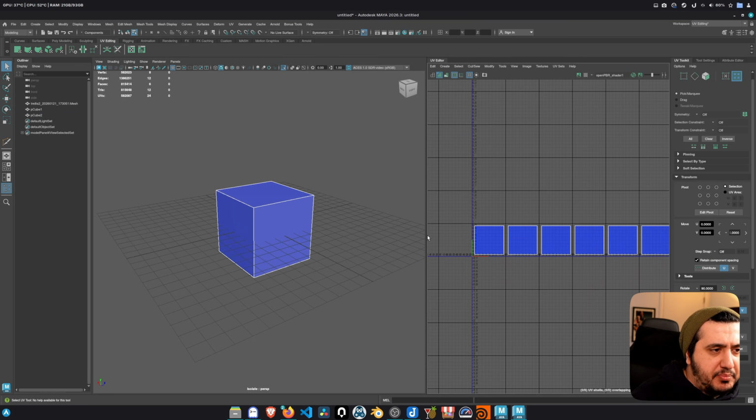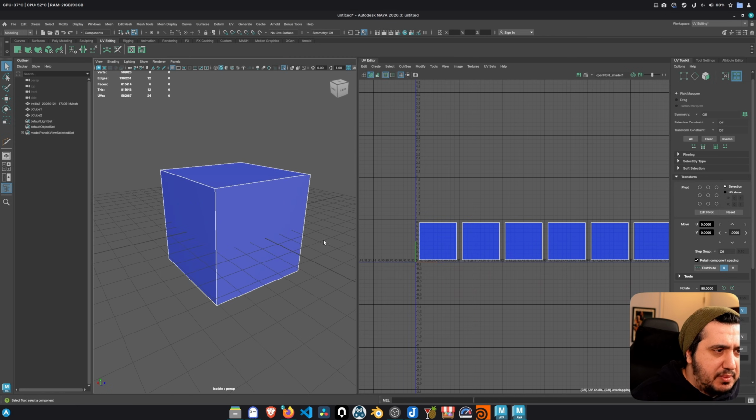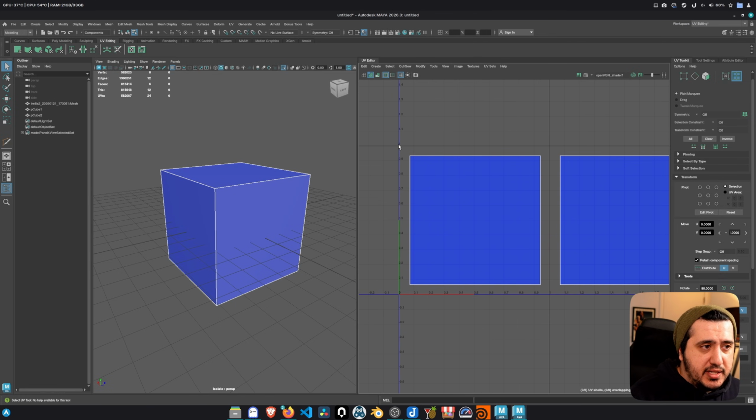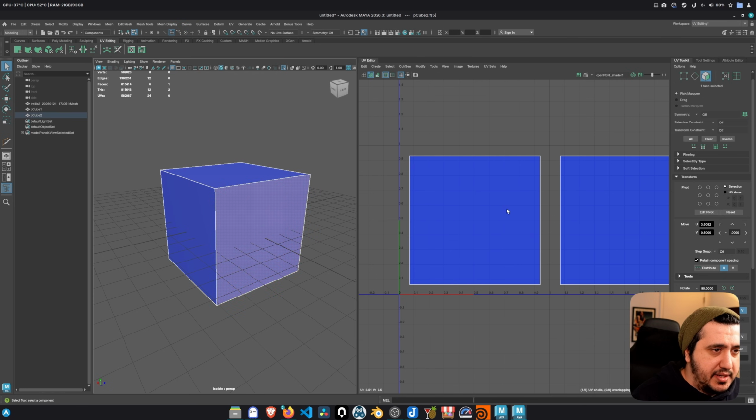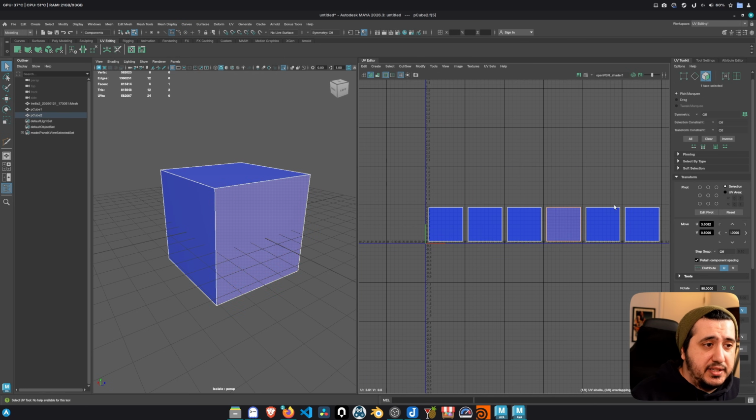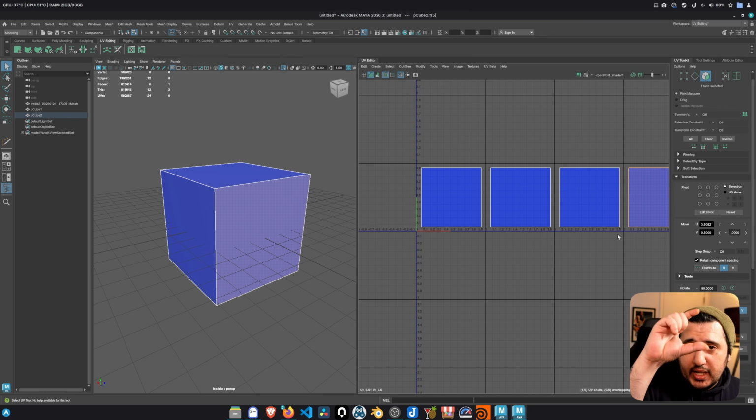Then we want something like that with a very hero asset, because now what I am doing is increasing the texture resolution. Think about this as your, let's say, 4K texture map. Now we call this texture density. It is the amount of texture data this little guy, in this case, let's say this face, is going to get, rather than all of the faces in one UV tile, which is going to be a 4K map. So we are increasing the texture resolution.